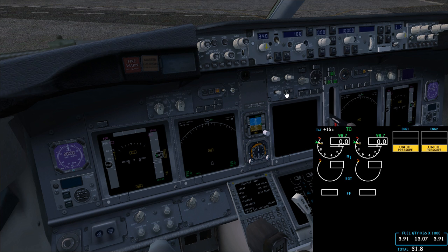If you press the first MFD engine switch here, the lower DU goes off, and we have compressed engine information on the upper display. As you can see here, we have indication with only parameters. These parameters are white. Not everything is displayed here because the engines are off, but we have N2 percentage.